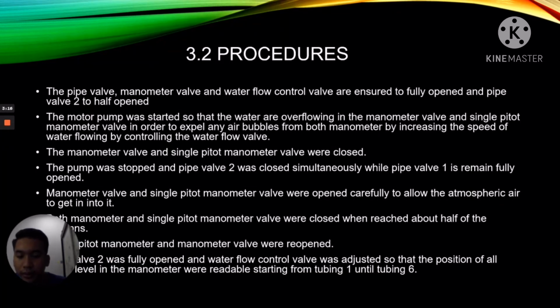So there are 13 steps that we need to do when we conduct this experiment. Step number 1: the pipe valve, manometer valve, and water flow control valve are ensured to be fully open, and pipe valve 2 to be half open.